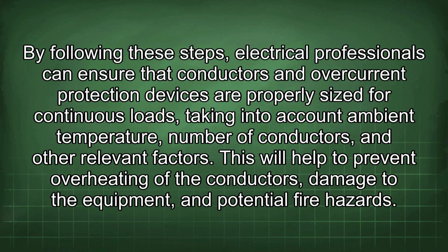By following these steps, electrical professionals can ensure that conductors and overcurrent protection devices are properly sized for continuous loads, taking into account ambient temperature, number of conductors, and other relevant factors. This will help to prevent overheating of the conductors, damage to the equipment, and potential fire hazards.